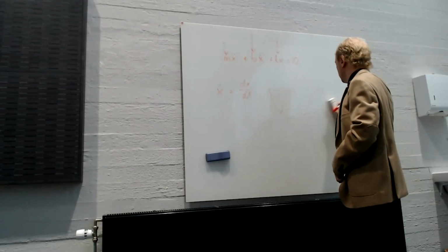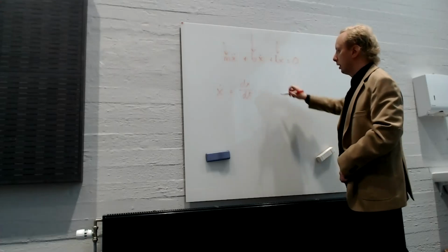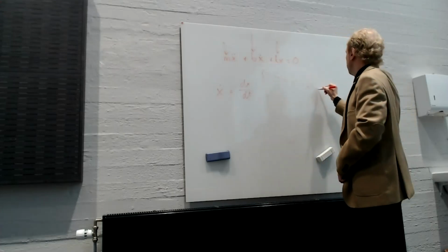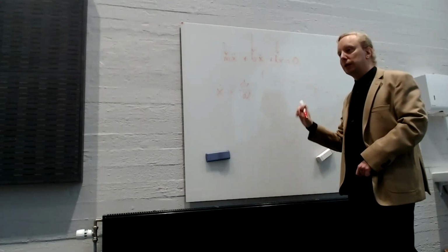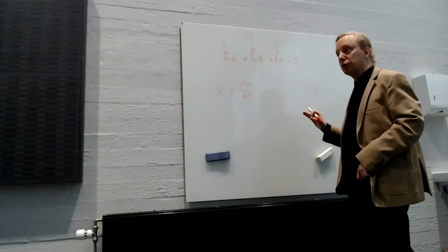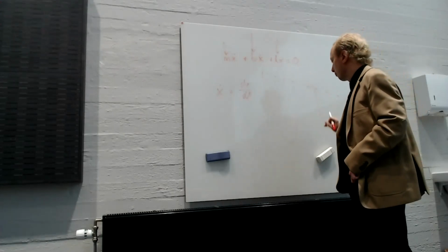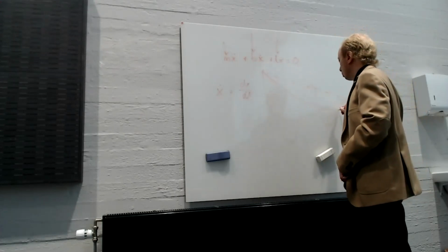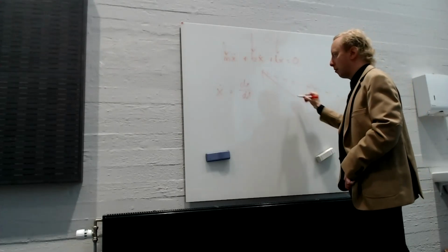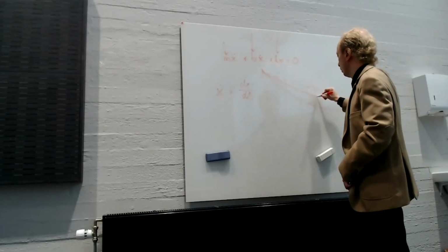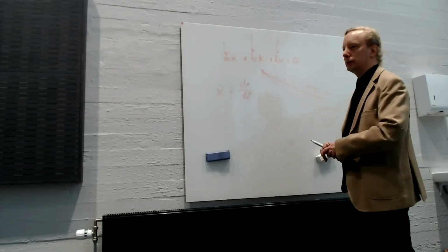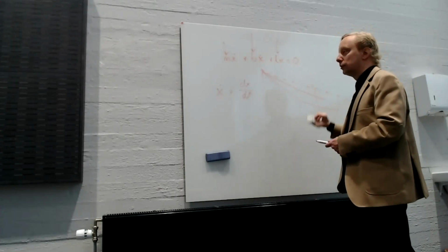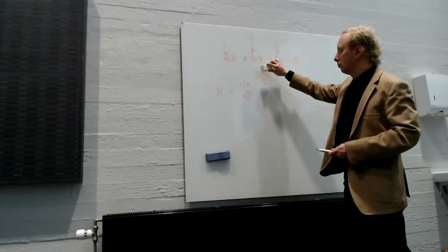When we have a so-called under-damped system, we get oscillations that go down along some exponential curve, but mathematically speaking they oscillate forever. Of course, we're going to have friction and we're going to stop sometime. Critically damped is when it goes to 0 smoothly. Then with over-damping, it actually goes too slowly to 0 because the damper is slowing it down. That's also the reason why in cars it's not good to have too stiff dampers.